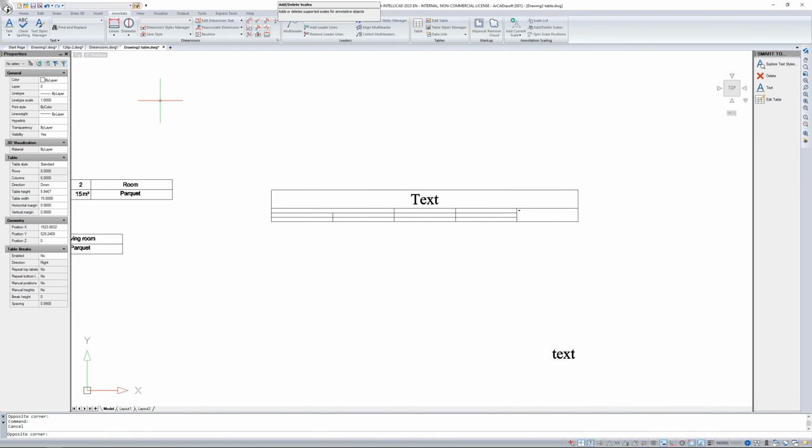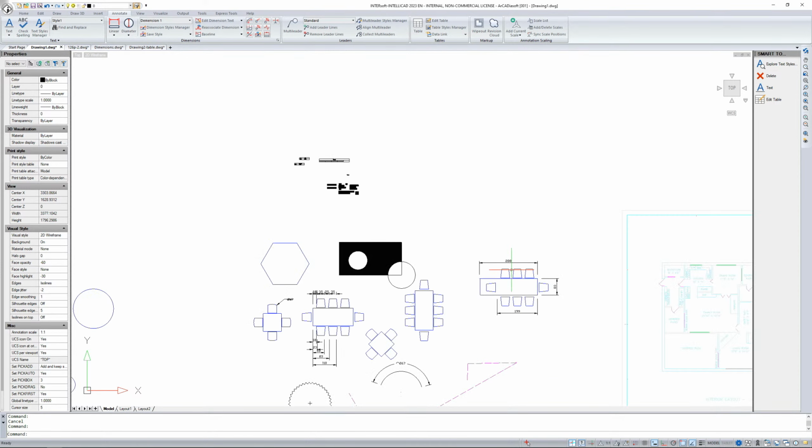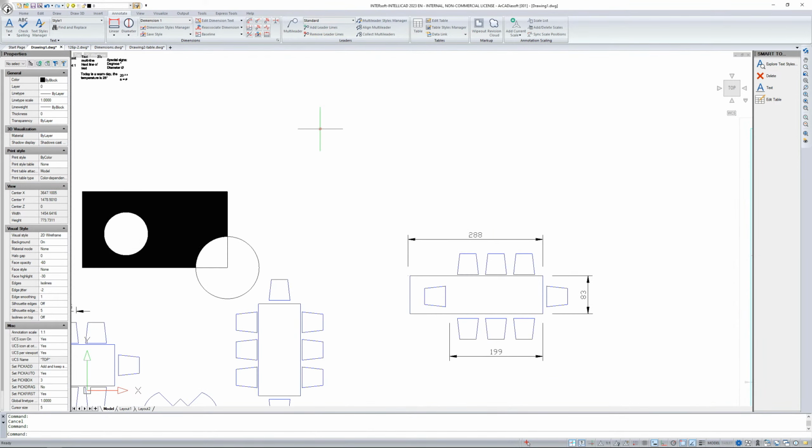And now I just wanted to show you something like the inquiry options, because sometimes it comes in rather handy. I mainly use the distance option by entering dist. I show a part of what I want to measure only to see what length or angle it has, because I need to know, but I don't want to have it left in the drawing.